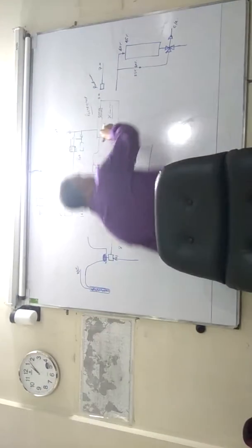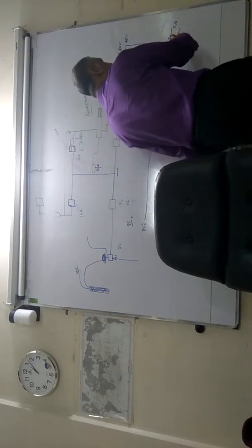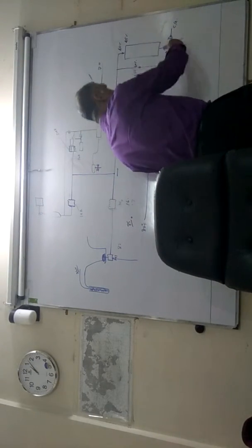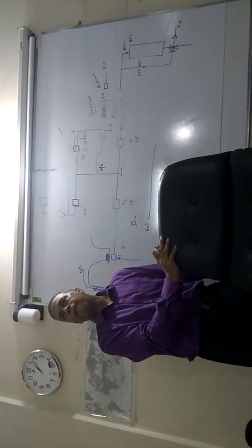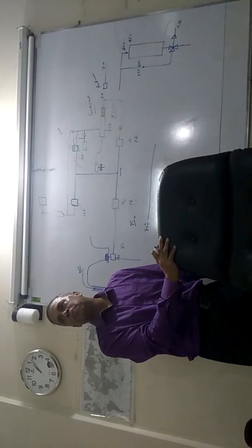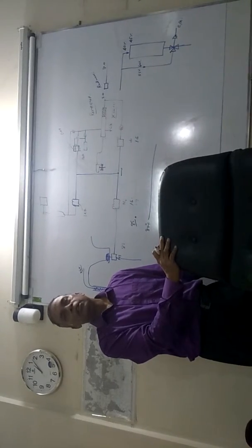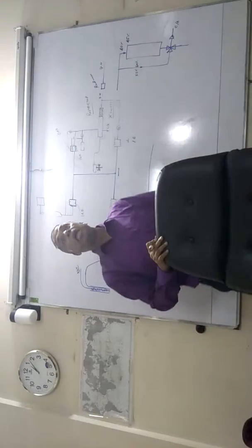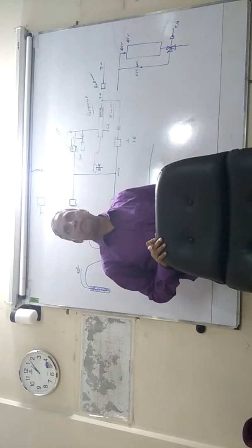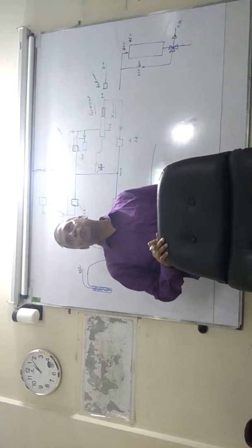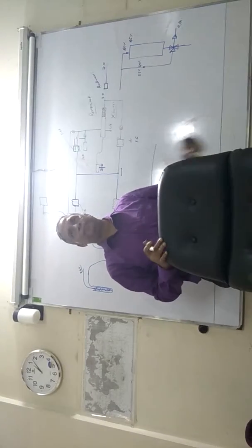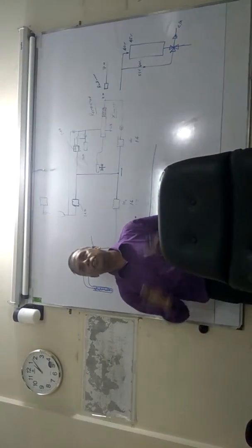If nozzle is closed, the pressure here is 2.0, the pressure here is 2.0, all the water passes through the cooler. Nothing is through the bypass. The cooling effect is at its maximum, highest level. The temperature correction will be very, very fast, which is all very good.